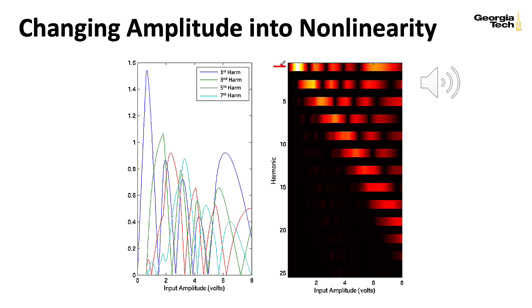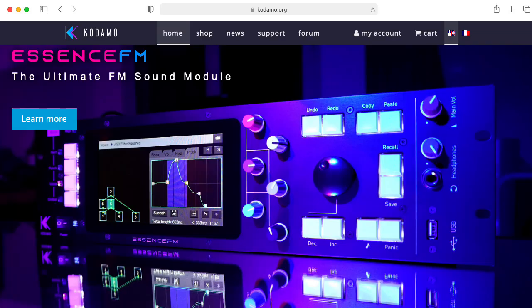So the first, third, fifth, and seventh harmonics that are indicated by those fast Fourier transform bins, I'm also presenting those on the left-hand side here on this plot. And you'll see that these harmonics fade in and out. It's not like you start cranking the volume and one of them goes up and stays going up. As one of them is fading in, another one's fading out. And you get these sonically complicated swirly patterns that are actually reminiscent of what you get from FM synthesis.